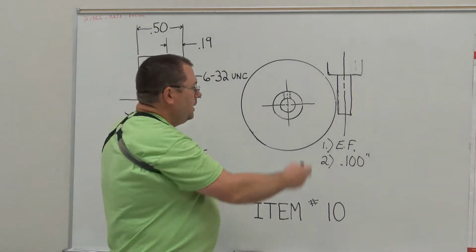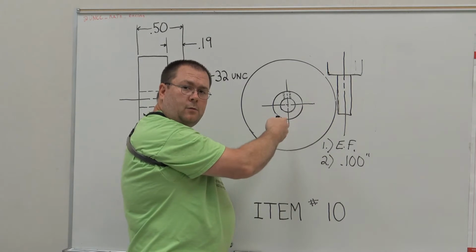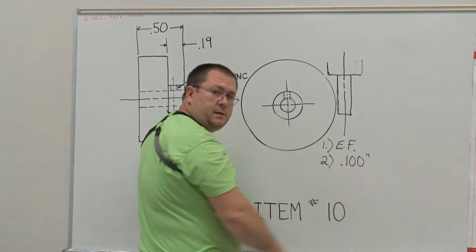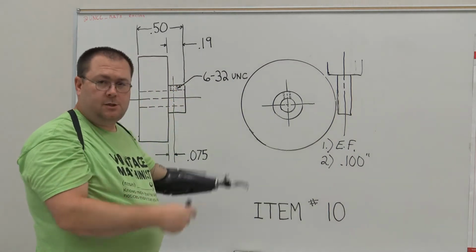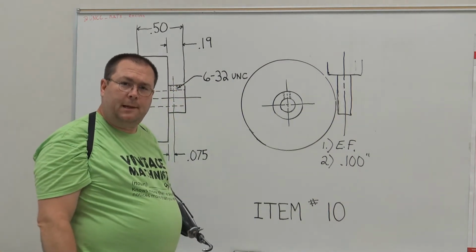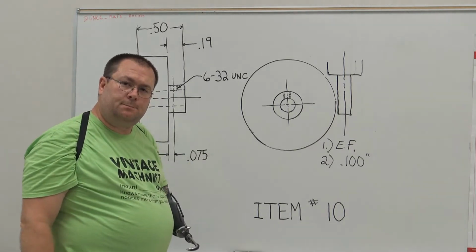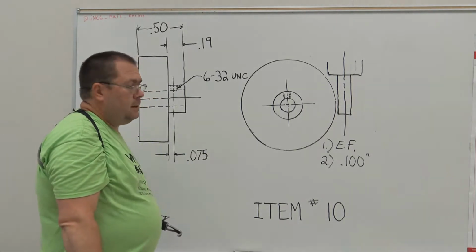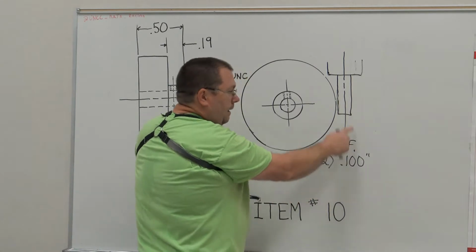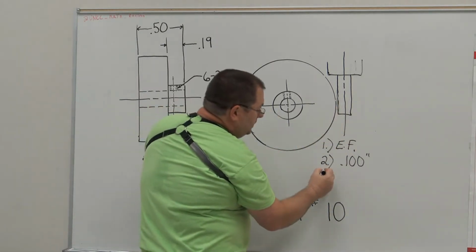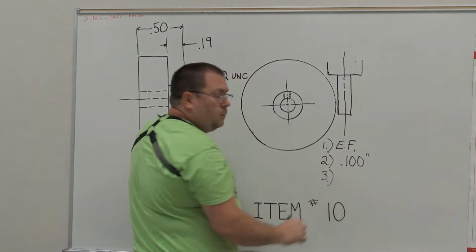Okay, because I said that I'd like to hold 5 thousandths to the center line, we would like to hold this dimension to 5 thousandths, and it just so happens that 3 decimal places is a standard 5 thousandths tolerance, plus or minus. Okay? So we've moved over half the edge finder, and then, next step, we're going to move